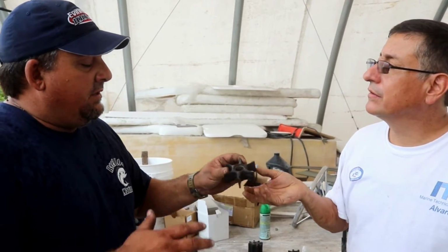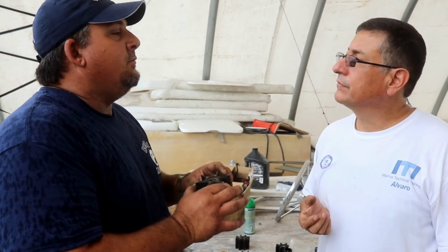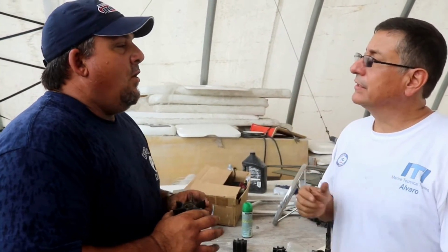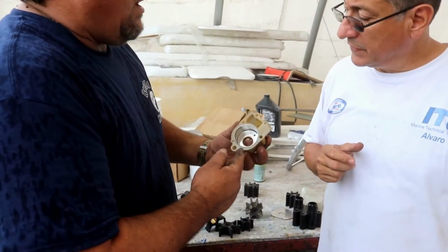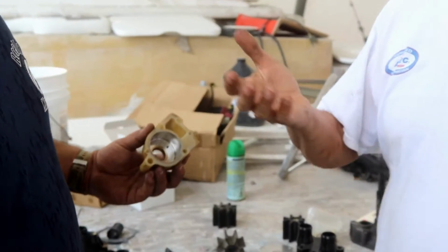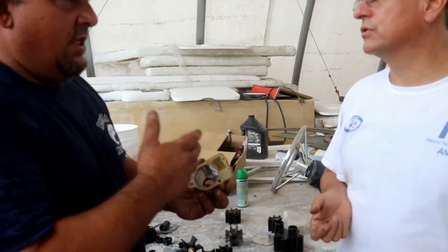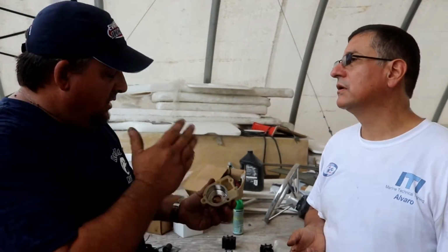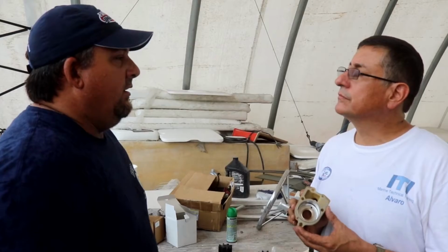What I always recommend to our customers is we don't replace just the impeller. We make them replace the whole water pump. Only because you don't know if there's a hairline crack in the housing. Imagine you put this all back together, you didn't see the crack, and you have to do it all over again. The customer's not going to pay you. So it's up to you as a technician to change out all the parts. It's only like $60 more for the whole kit.